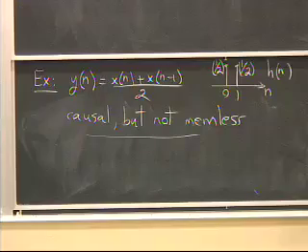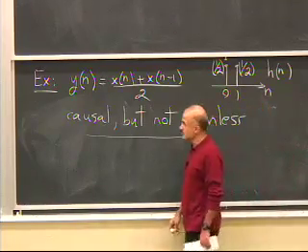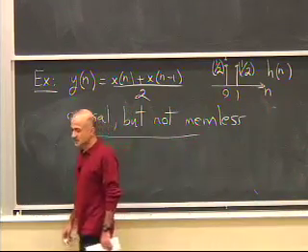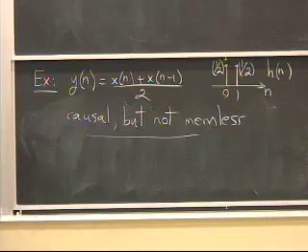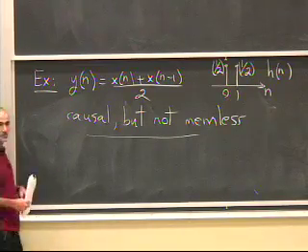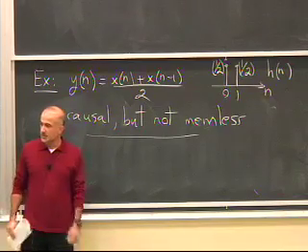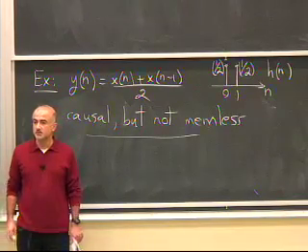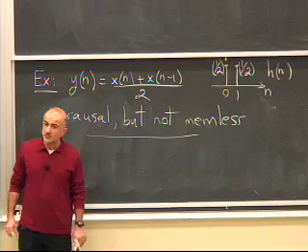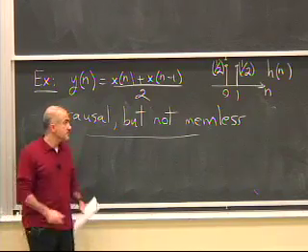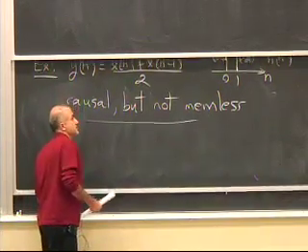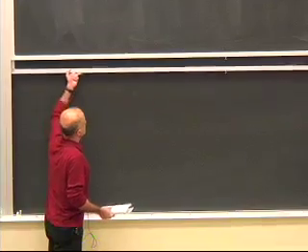Okay, so that's the relationship between memoryless systems and causal systems. What about memorylessness and time invariance? And this is where we diverge from the common literature on memoryless systems. If you pick up a typical textbook on signals and systems, they will differ with us on this issue. For our definition of memorylessness, every memoryless system must be time invariant.